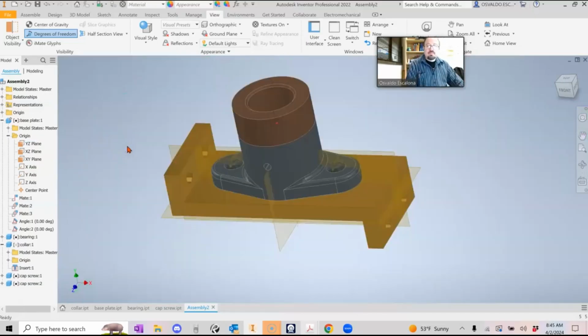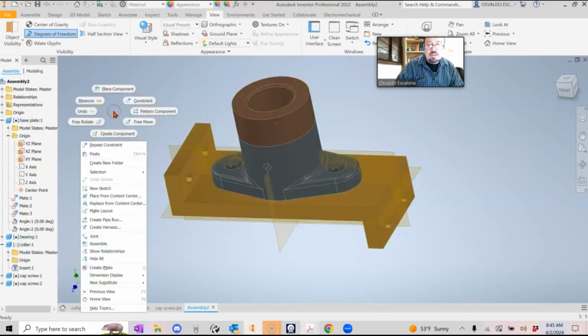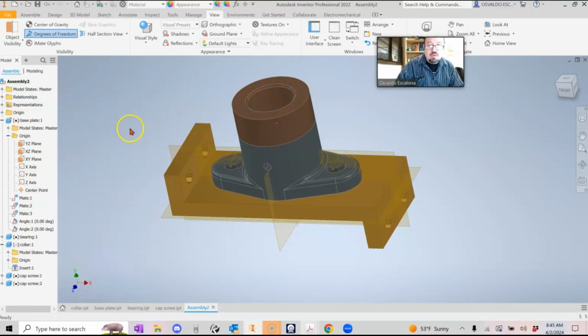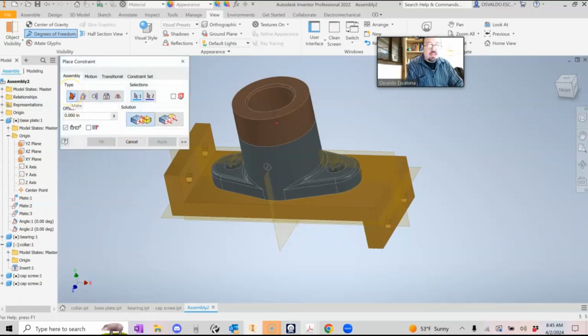All right. So how do you place a part? Again, the first part that you put should have a base to origin. That should always be locked. And then after you put the next components, how do you place a component? You just right click, place, look for it. And then after you place it, you can also constrain it. Once you do a constraint, you are going to have the mate that has two faces together, or 2 axes together. You can have angle, that was a face to a face, what would be the angle of it.